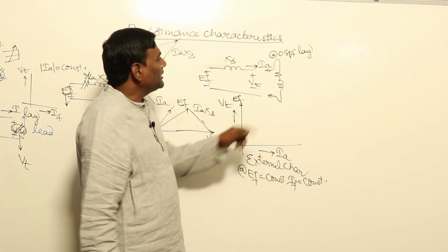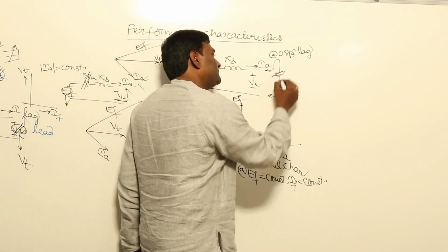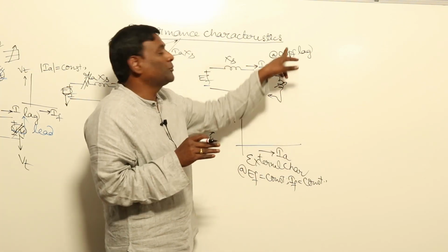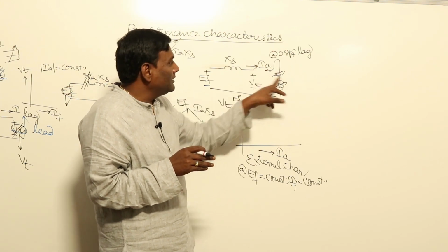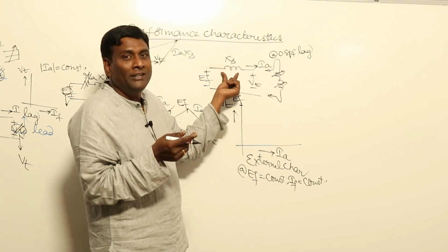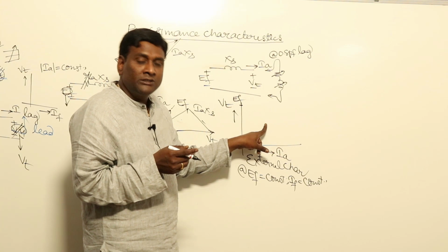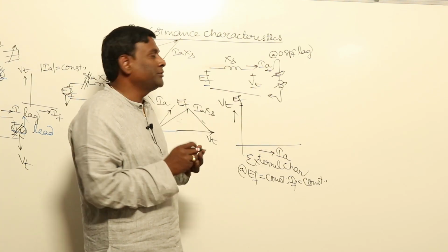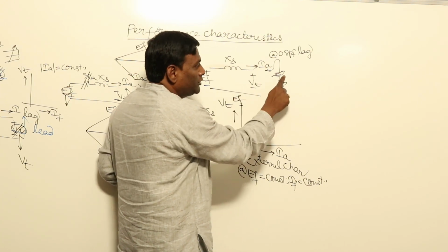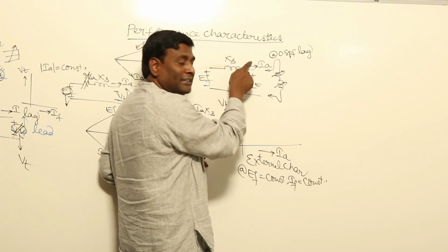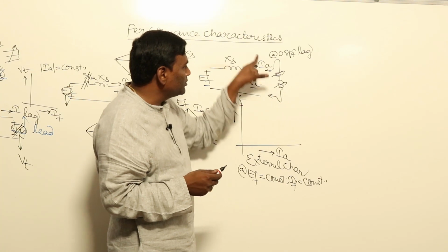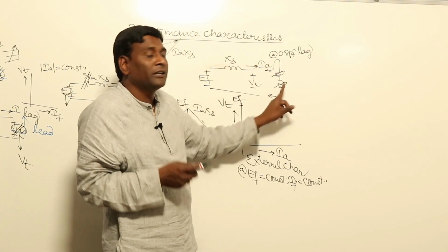Now for example, if I reduce this resistance still, and reactance is reduced in such a way that 0.8 power factor is maintained. Under that condition, total impedance is going to reduce, IA is going to increase. If IA increases, IAX voltage drop will increase, means that VT will be reduced still. EF is maintained constant, VT will be reduced. So total impedance reduces, IA will increase, so VT should reduce.